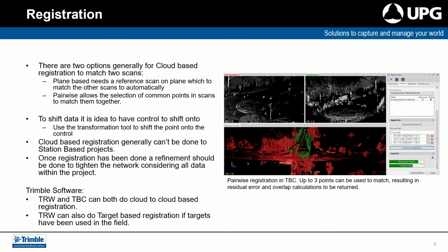This is where the registration tools come into play. Registration tools can also be used to break scan registration sets from, say, Trimble Perspective, where they are already linked together, to better fit the data or to address any registration issues as well. So they are not just limited to projects where the data has not been registered.